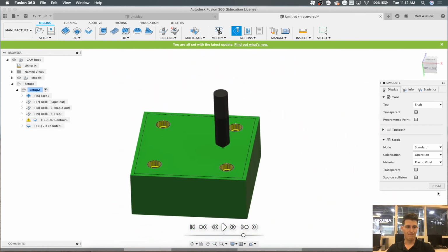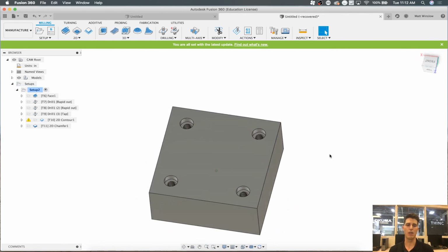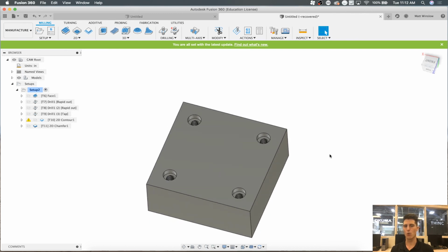Okay, guys, that's the basics of doing holes. Let's see, we've gone over tapping, we've gone over contours, roughing strategies, setting tooling, speeds and feeds, planes, etc. So that's a very basic CAM intro. That's enough that you can do 99% of what you'll need to do in this class if you learn those basics. So make sure to practice them. Come get me or Jeff or someone who's familiar with Fusion 360 if you have any questions. But otherwise, it's just a matter of playing with this.